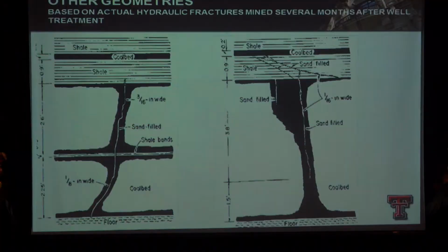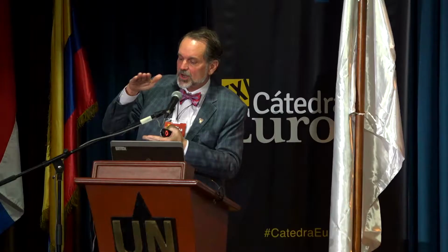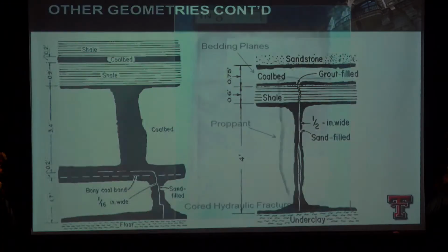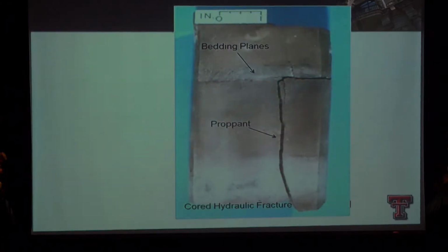So we pumped the hydraulic fracture treatment after drilling these wells, and then actually mined to the well so we could actually visually go down in the well and see the fracture as it formed. And you can see this is less than 1/3 of a meter, a different type of rock that has stopped this fracture from growing up. And that's only 1/3 of a meter. Same thing here, same thing here. Here is an example of a mined product, this rock that we have, this bedding plane that's only a few centimeters, that has stopped the fracture from growing up. So this is how we know, both from the mechanical properties of the rock and actual data we collected, these fractures don't continue to propagate up and up and up.